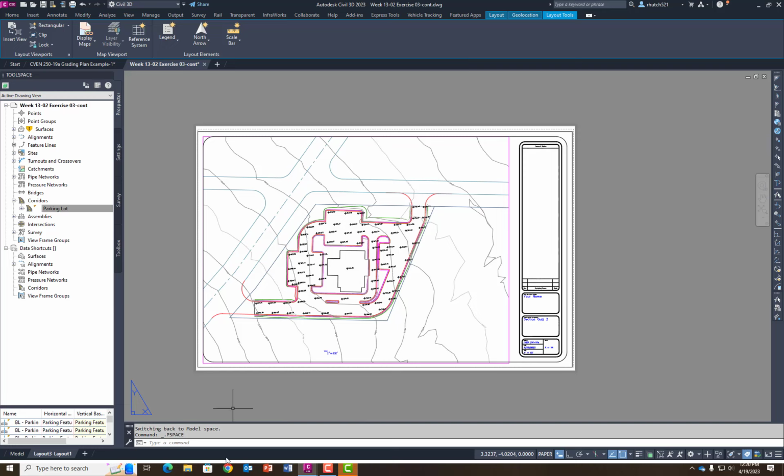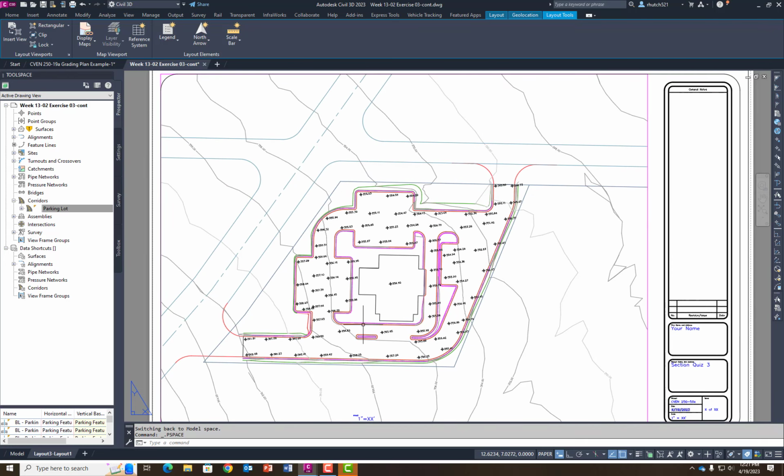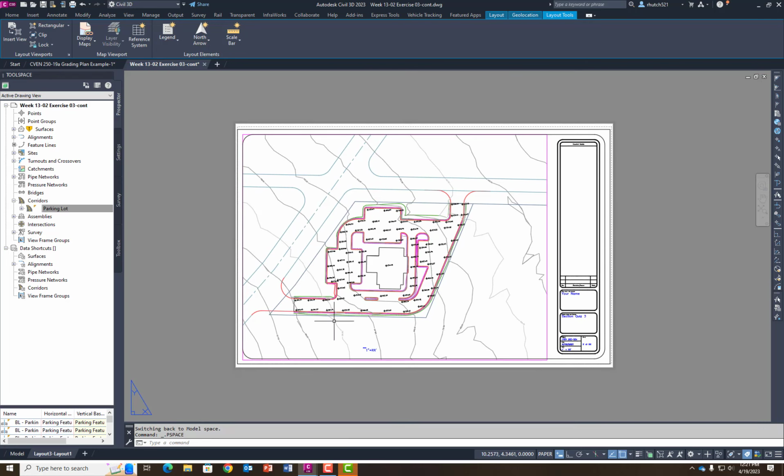So this is all the steps needed to get from where you set up your reference surface, projected the lines up to it, added the corridor, created the surface, created the final surface, and then the last little bit, like adding in spot elevations, making sure your lines are all showing up that you need in your design, and leaving out the ones you don't. If you notice, the ones that I used to create the reference surface aren't on here because those are just distracting in my design, so I didn't add those in. All right, so that's how you create this type of design and get from the first part of Project Homework 4 to the finish.